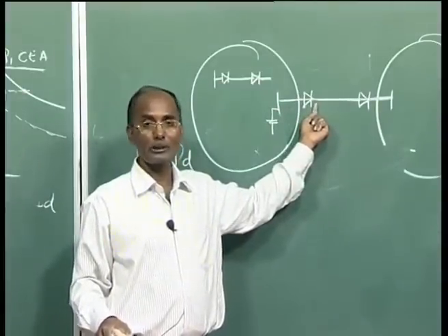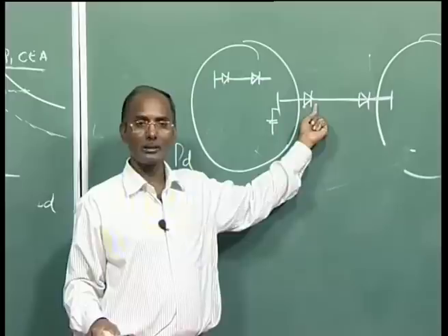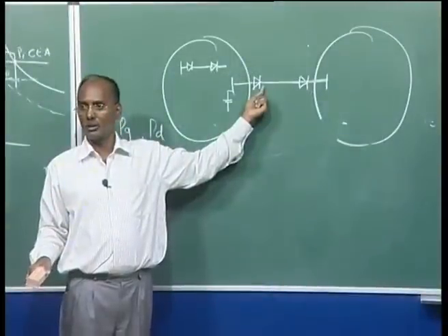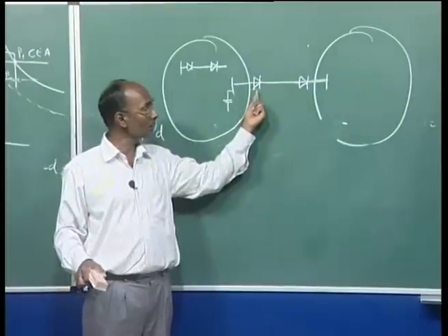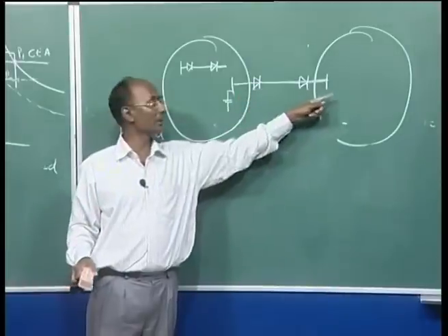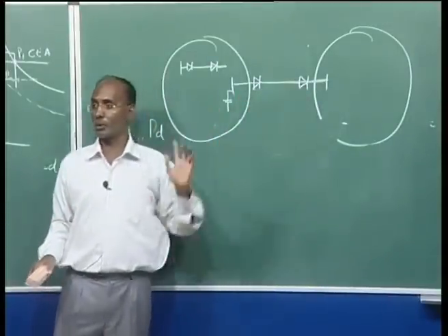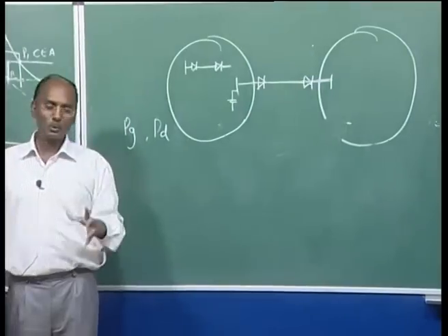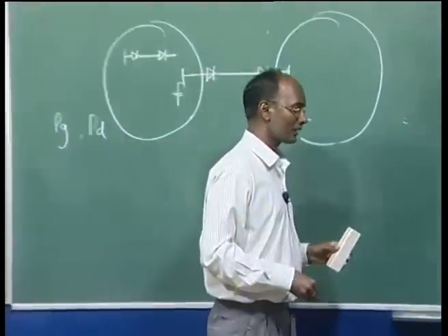But it is not advisable. We never do it unless you are really in an emergency. Because if you are changing this alpha, then gamma should also be changed accordingly to maintain the power here. And then it will be absorbing more and more reactive power from the system. So you can do this reactive power control only to a limited extent, especially in really critical conditions, when voltage stability problems and other things are arising. But still, in normal practice, we never do reactive power control with the HVDC link.